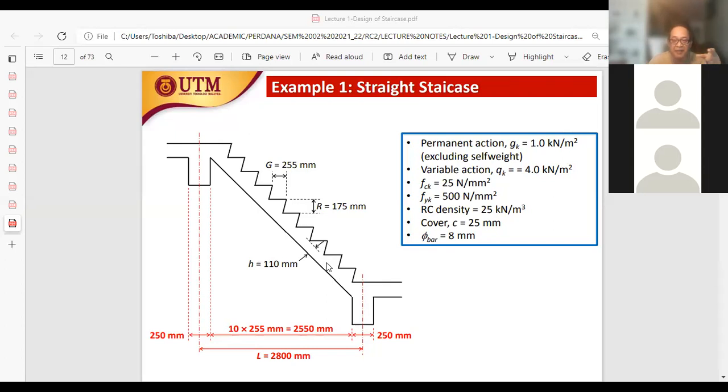Okay, so if the building, katakan at the start of the design, we have taken the building, 3-story office block to be 1.5 hours fire resistant, 90 minutes. Jadi based on that 90 minutes, dalam table tu will give the minimum dimension thickness untuk slabs, dimension for beams, dimension for columns pun ada di situ. So that table ataupun that reference based on the fire resistance on a building will give a very useful indicator untuk come up with a certain dimension.